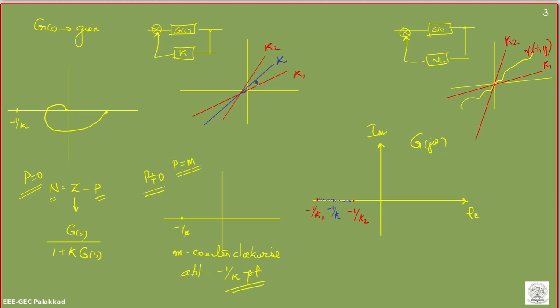But since K is not linear, we have another way of analyzing the stability of the system. From the feedback condition, what did we get? For the nonlinearity lying within this sector, we had to check for some G hat of S which is positive real.